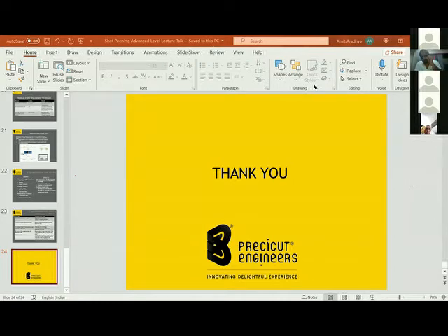Ideally, if you go through SAE standards, what they say is the shot size should be half or maybe 30-40% of the radius at the gear root. So if the shot size is higher than that, then there is a problem of shots sticking in the tooth or whatever area is being shot peened. So the size needs to be reduced. We have to check the radiuses over there.